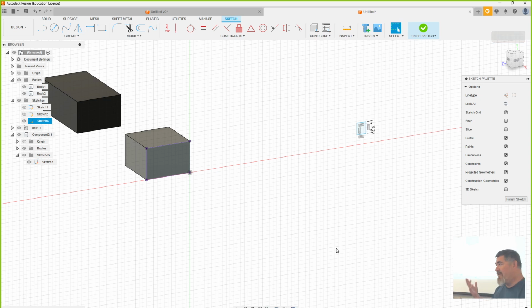A lot of people will do this when they try and do big, complicated sketches. They don't want to realize they messed up and don't want to have to do everything again. This is part of why I say keep your sketches simple. If you're doing simple sketches, it's faster just to make a new sketch than it is to try and copy and paste and rescale and redo everything, right? If you've only got 6 pieces of geometry, just redo it. Don't waste the time trying to copy and re-constrain everything, it just makes much more of a hassle than keeping it simple.